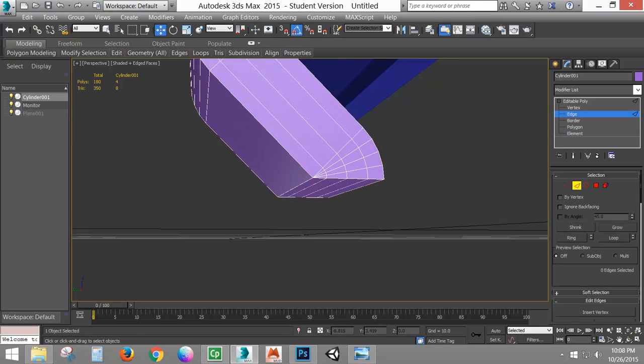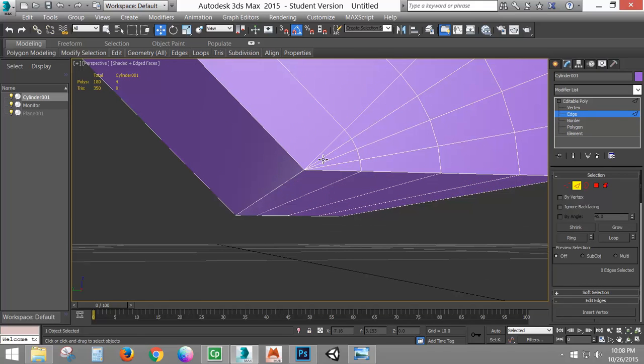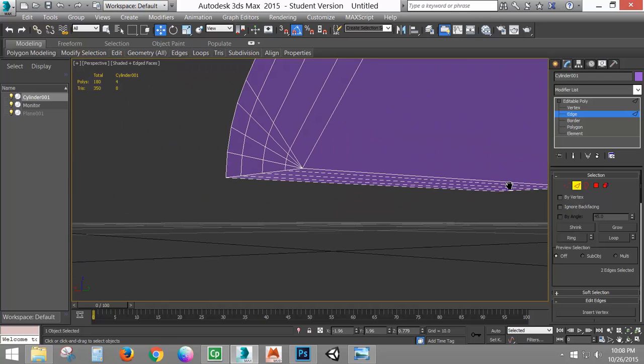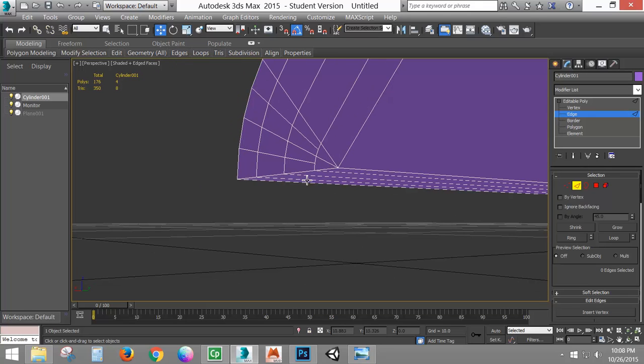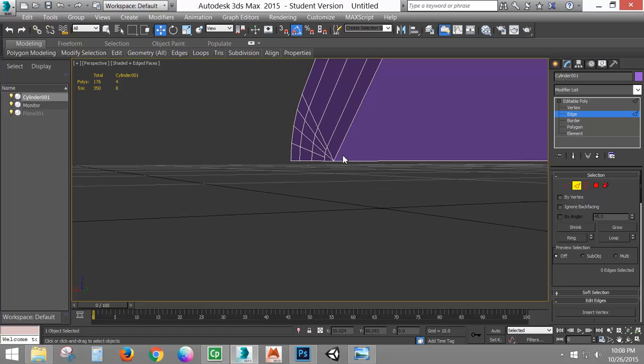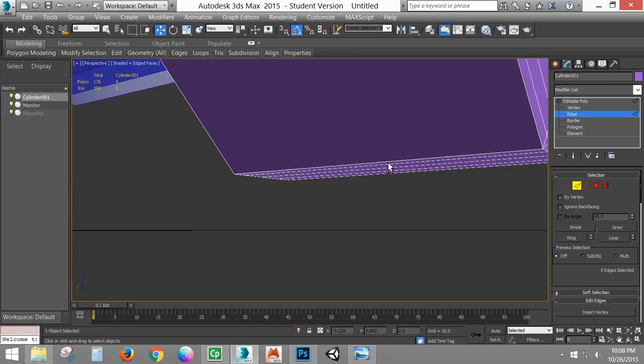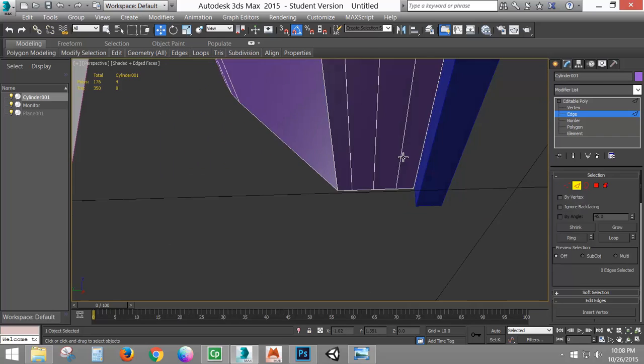I'm going to do the same thing with the edges. I'm going to go to where all 4 of these triangles have been created. I'm selecting basically every other edge here on both sides. Control Backspace will remove those. I could just hit Backspace, but I'm in a habit of hitting Control Backspace because when you hit Control and Backspace, you'll also remove vertices that may be undesirable. So in this case, it wouldn't matter either way, just based on how this is.